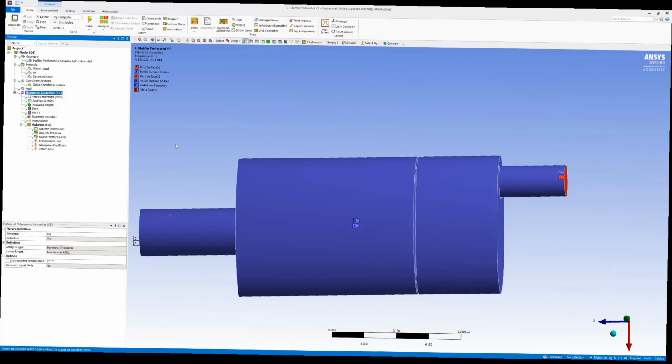Say you put a pressure transducer inside, or before your muffler, you can use that wave source and its magnitude and its frequency to have a realistic input through your muffler.